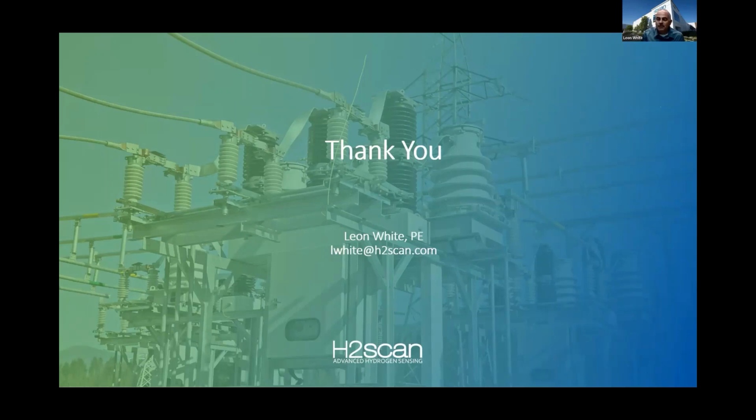It really depends on your circumstances, your transformers, and your experience. Some people have a failure rate of about 0.5% a year, some are up around 2 or 2.5%. Again, your experience, with not only the transformers but also the monitors, can allow you to extend the time between samples.